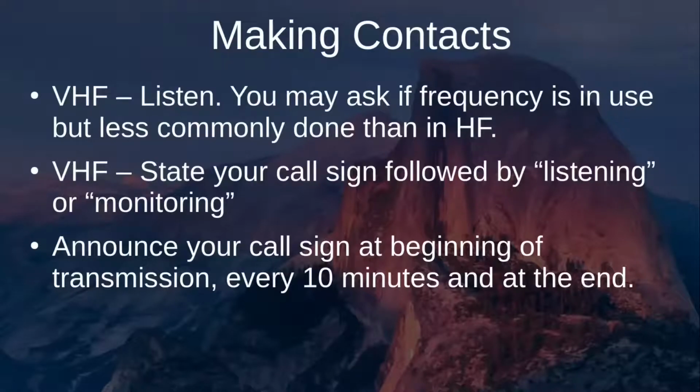You would just state your call sign and say listening. So this is N9WIB, listening. And then you would wait for a response. And if you haven't heard anything after a minute or two, you may come back and try again. Say N9WIB listening or N9WIB monitoring.